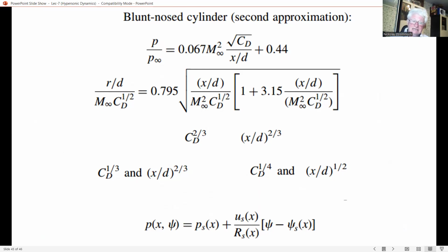Second, the thin shock layer method. These methods make use of approximations based on the thickness of the hypersonic shock layer. As an example, Maslen's method is a straightforward application of the thin shock layer assumption, leading to a closed-form equation for the variation of pressure across the shock layer.